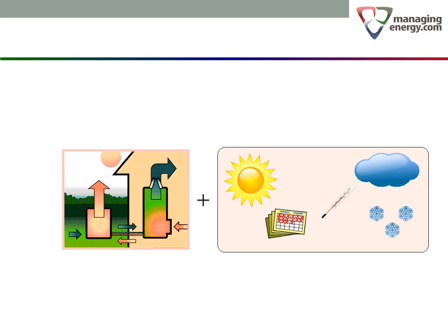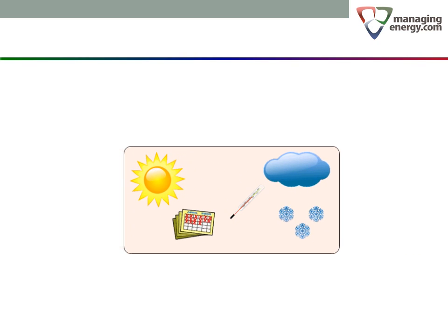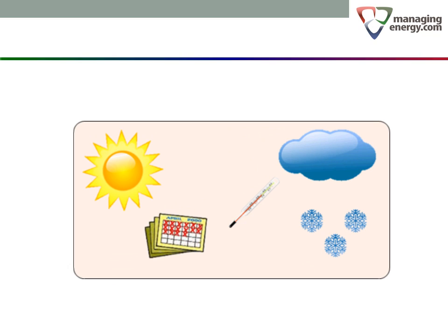While all this is certainly true, we're going to concentrate on weather and leave the discussion of other independent variables for another video. Experience shows that in most commercial, institutional, and residential buildings, weather is the dominant variable and often the only significant one. Year-over-year weather variation can easily change heating or cooling requirements by 20 or 30%.